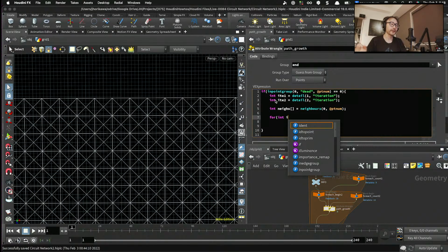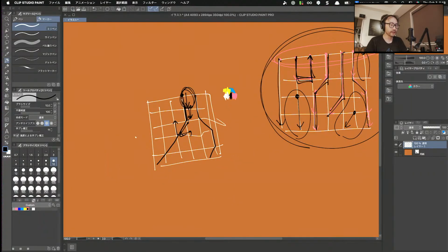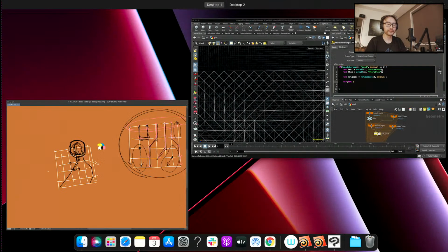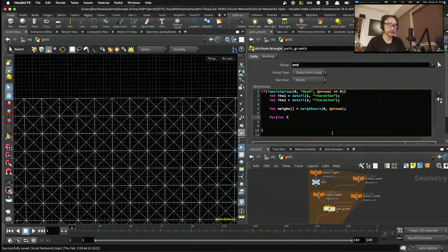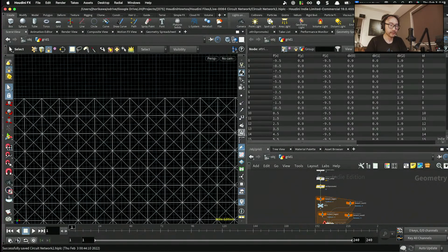In order to pick that, as I said, you want to refer to the previous direction that you have set inside the point as a dir attribute. In this case, this one, the dir attribute. So right now it's 0, 0, 1 for everything going downward.